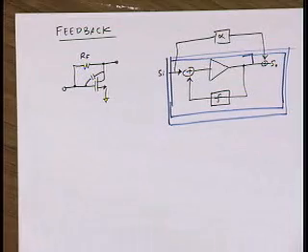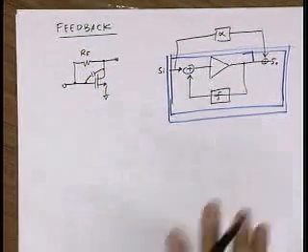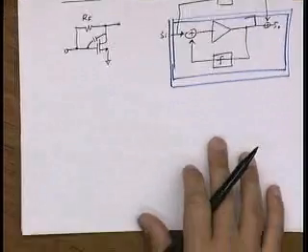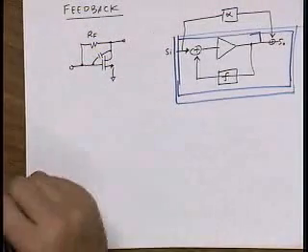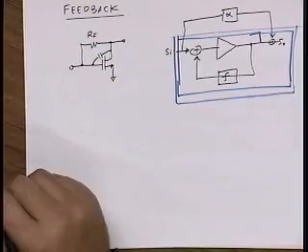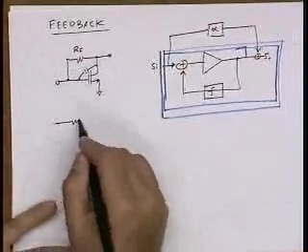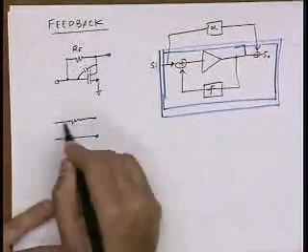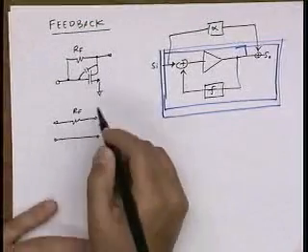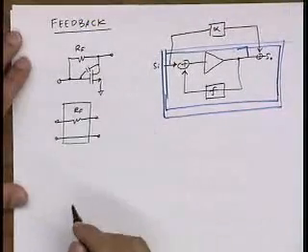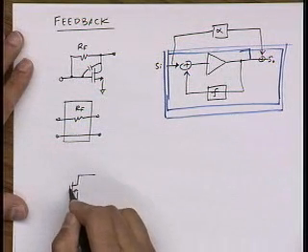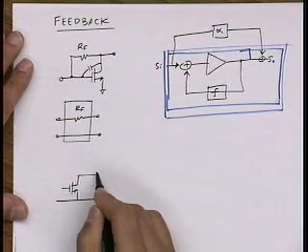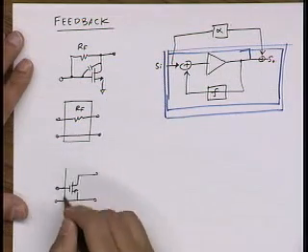Okay. All right. So let's take the approach that we discussed last lecture. So last lecture we made the observation that we can analyze this amplifier using a two-port approach. We can break it up into two ports. So we can consider the resistive feedback network as one two-port, and I'll draw a box around it to emphasize that. And I can consider my transistor as another two-port as follows.